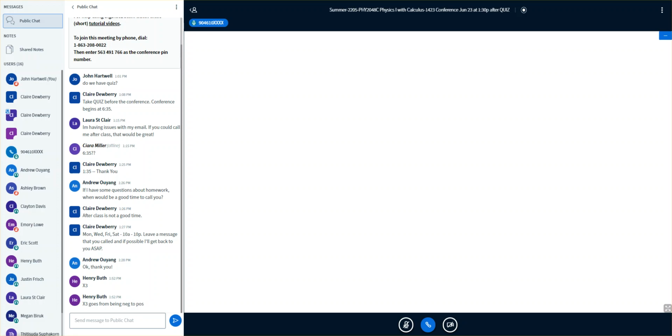Okay. Here's where it decides that the speed of the crate when it arrives at the bottom of the ramp may be so large that its contents may be damaged. And they talk a little bit about what angle then you would like to move the ramp. There are tables for this kind of stuff, but this is how you develop it. And I take exception to the fact that they did not write the equation that they've been developing. If you want to pursue that, that's fine, but I'm not interested in it.